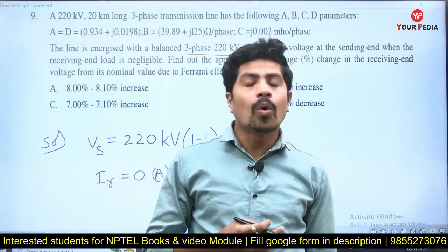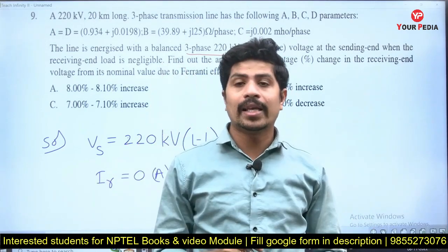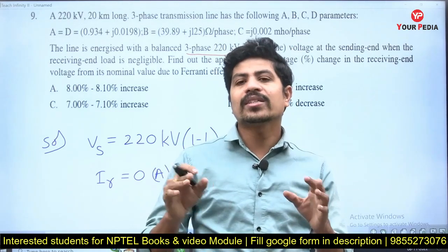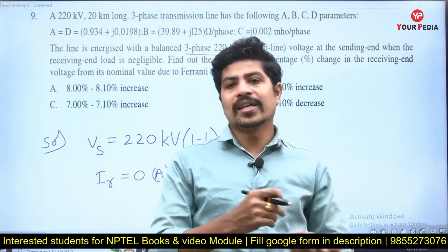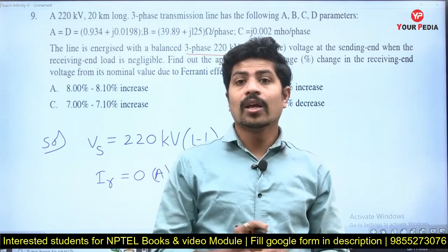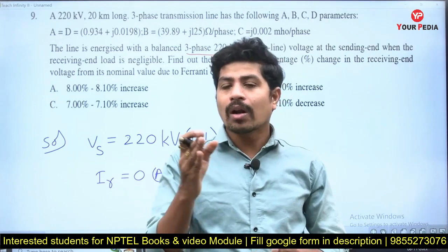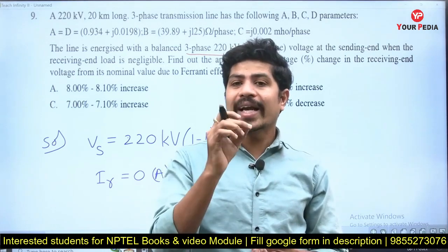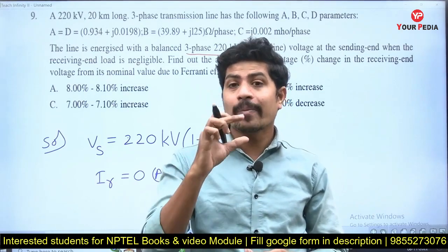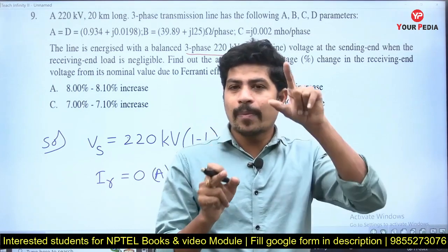Practically, mostly 99% of our loads are lagging loads. Therefore, most of the time during loaded conditions, the voltage will be less than the sending end voltage or less than the rated value. Voltage drop will take place. There is no question of voltage rise during lagging load practical conditions. But if the load gets removed, the only current flowing in the transmission line is the charging current absorbed by the shunt capacitances of the transmission line. We are not connecting any shunt capacitance to the transmission line.